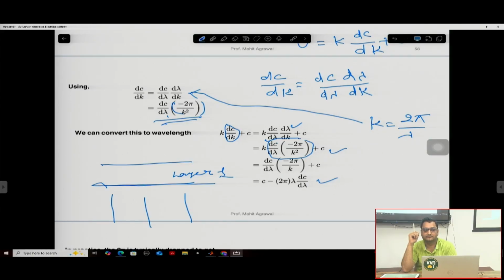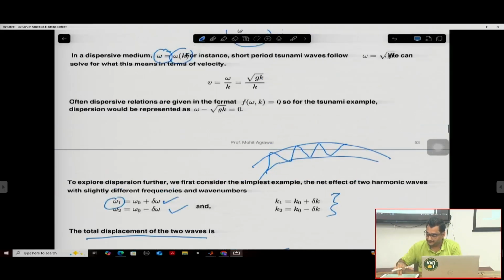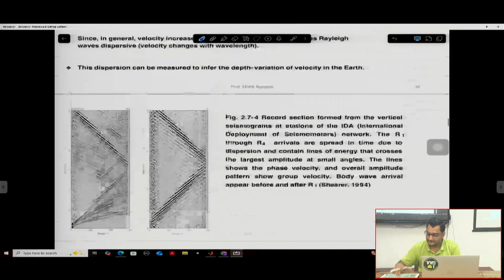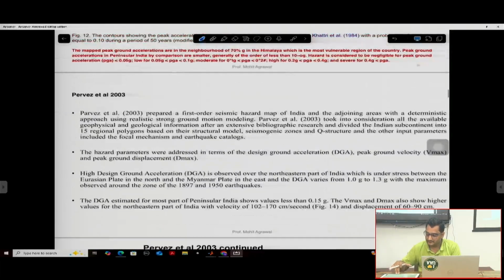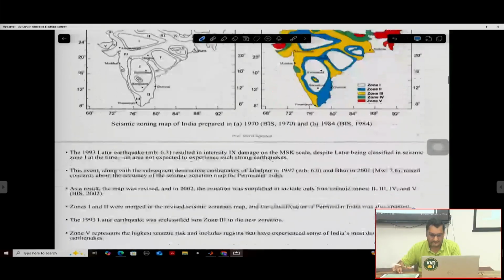Excellent. This question is for Gupta sir. Are you sure the slide with the number of source zones is of RTR, 1999, where it is 86? No, those were source zones. Yes. So depending on source zones, whether the PGA value changes for each source zone, suppose we reduce the source zones from 86 to 20. So for each node, the PGA will change. Yeah, the PGA will change because you are considering a lesser number of zones.